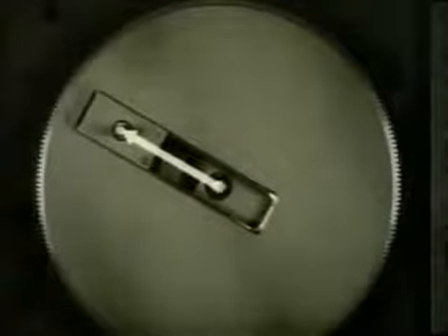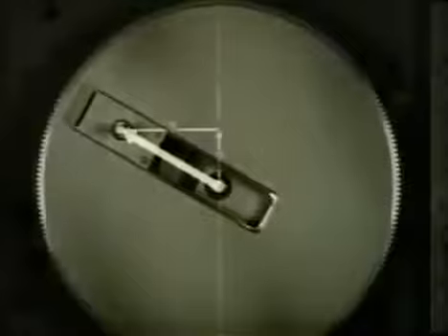Now that we know how the speed vector is produced, we next want to see how its components are obtained to complete the vector diagram. For this, there are two slotted racks, with the pin extending up through both slots. As the pin moves to form the speed vector, it also moves the racks to form the vector's components.